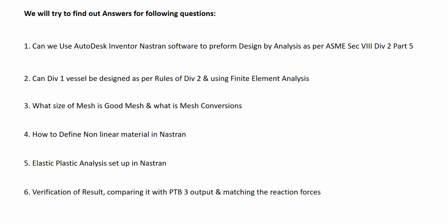Another interesting topic we will be discussing today: can an ASME Section 8 Division 1 vessel be designed using the rules of Division 2, and more precisely using the finite element analysis method? Another topic I will be covering is what is a good mesh to continue the analysis, and how to know what mesh convergence is.